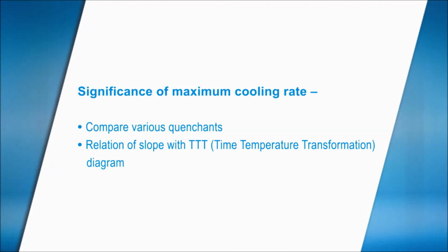Significance of maximum cooling rate. The maximum cooling rate can be used to compare various quenchants. The relation of the steep slope of the temperature versus time curve and its position in relation to the time-temperature transformation diagram is of utmost importance.